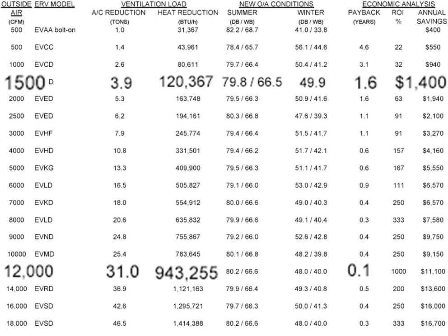Now in defense of this number, the reason why it's such a good payback is most of you guys know with rooftop units, like I said on week 1, if you can get down below 30 tons, down to that 25, 28 ton rooftop chassis, you are more in line with a quote-unquote commodity rooftop unit as opposed to a semi-custom rooftop, so the cost goes down dramatically. So that's what happened in this case. We're able to get into a much smaller chassis unit where the cost was much lower for the unit itself, which made it easier to pay back the ERV because of the rooftop cost savings when we bought the new rooftop.